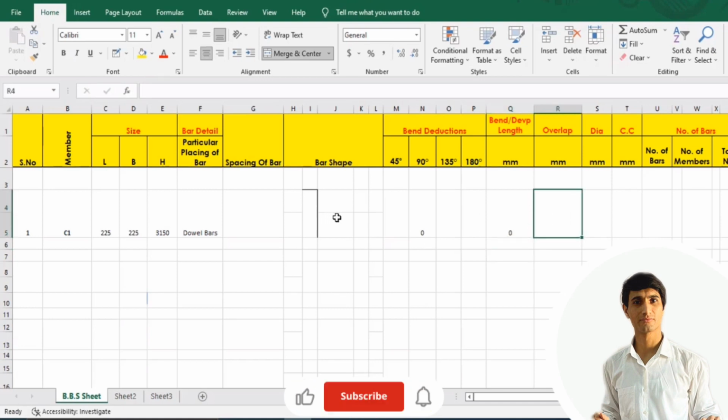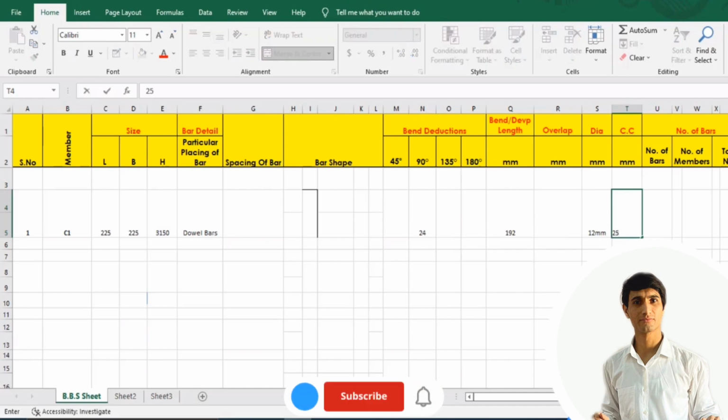We have already found the overlap value. Now we'll find the straight value and then the development length. Next to it, we have the dia of the bar, and the dia that we are using here is 12 mm, and based on this you can see the values over here. Concrete cover in the column is 25 mm.